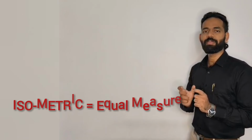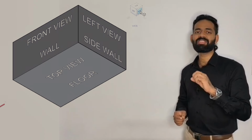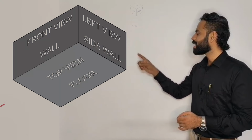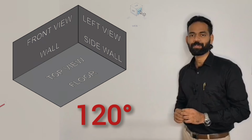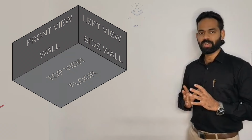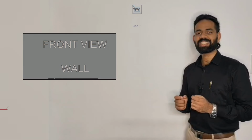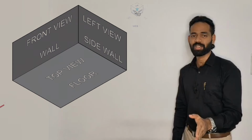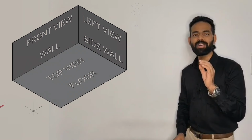The word isometric means equal measure. So the three dimensions or the three axes are represented here on a flat surface with equally inclined angles, that is 120 degrees. So every horizontal line, that means the length axis and the depth axis, is tilted 30 degrees here, and the vertical axis or the vertical line is kept the same. This will give a perfect illusion of the 3D object.